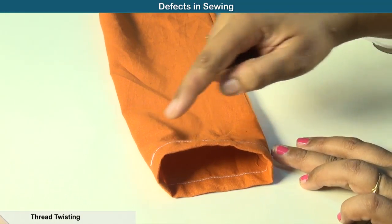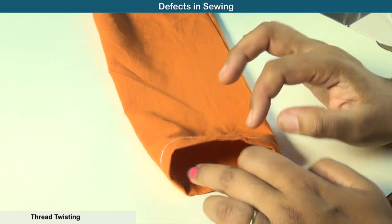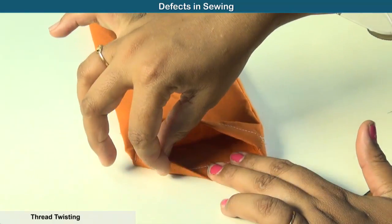Now we gave a bottom edge stitch. You can see a twisting here. It should be flat, but you got some twist here. So this is known as twisting.